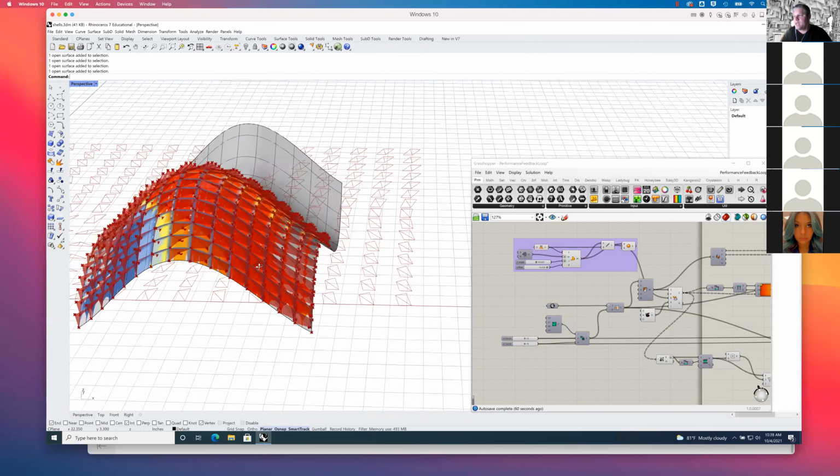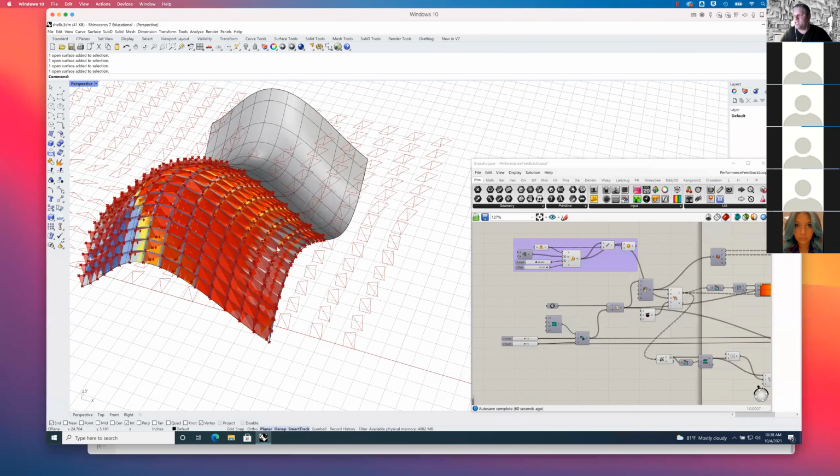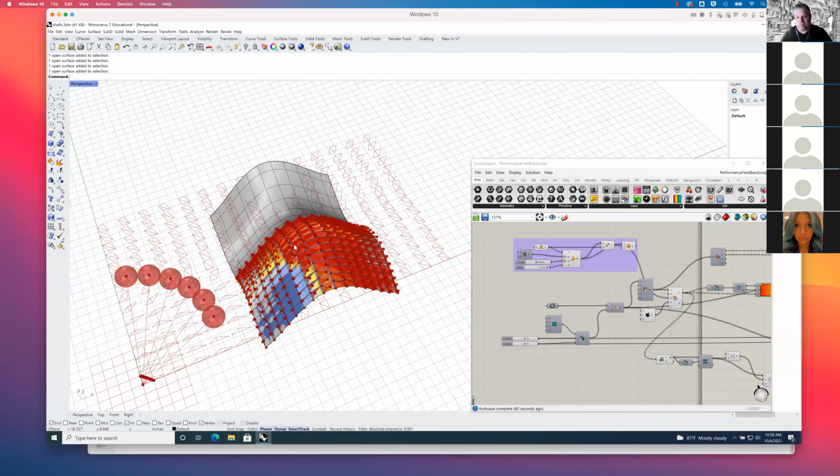In order to provide shade where you need it, right? What's interesting about this is you can start to use the parametric model, take the performance constraints and actually use it to generate this differentiation that occurs over the course of this grid to create a gradient, not just in coloration, but in the geometry itself, so that the parts where you need larger, closed off shading components that close off the cells in order to create shade can, and the ones that don't are much smaller and actually allow views in and out.